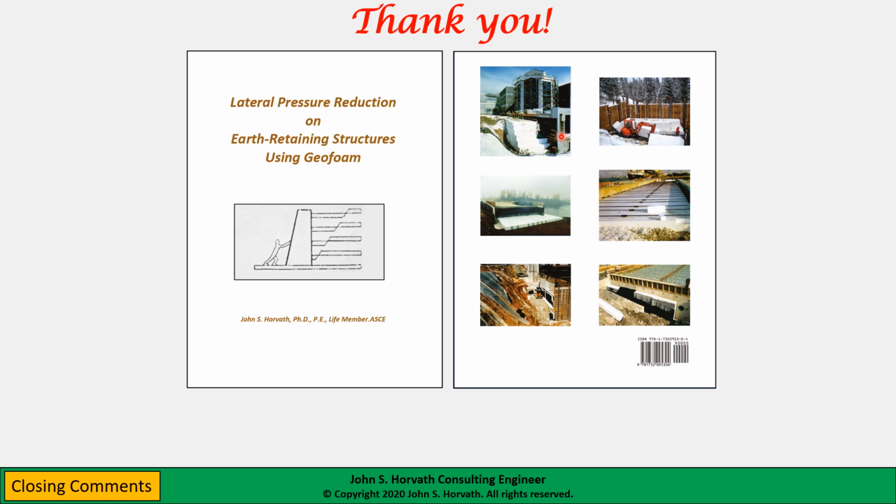and all the structures were supported on deep foundations. So in addition to reducing lateral pressures on the below-grade walls of the parking garage, they were concerned about settlements outside, because this area here was all at-grade parking. So this was actually a good choice in this case, because by using EPS blocks, they were able to minimize the settlements that occurred outside the structure. But as I said, nowadays we would certainly stair-step these blocks. But nevertheless it was a successful project.